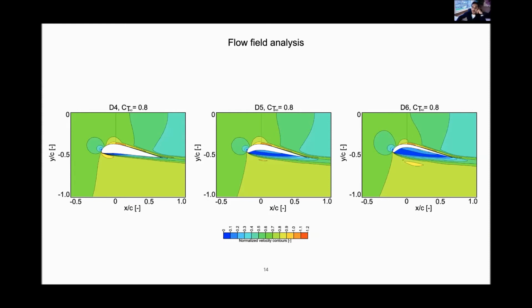The figure on the top right would show that decreasing with the increase in camber. This is because of the separation that you see in the blue region, which traverses from the lower part of the duct to the upper part. This induces additional flow separation inside of the duct, leading to the power drop.